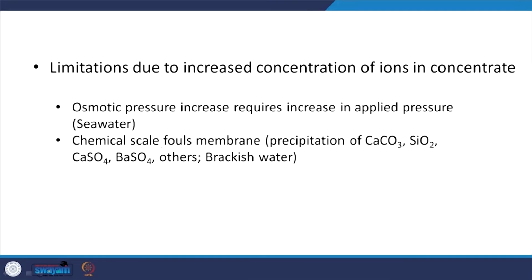Again, as I just mentioned, the limitations are due to increased concentrations of ions in the concentrate, right. Osmotic pressure requires an increase in applied pressure, right. This is the case especially with seawater. Osmotic pressure leads to an increase in the applied pressure, and that means again you are going to have fouling.